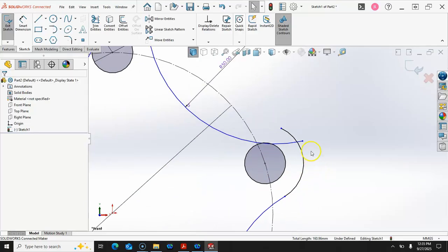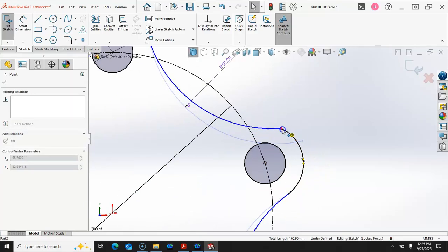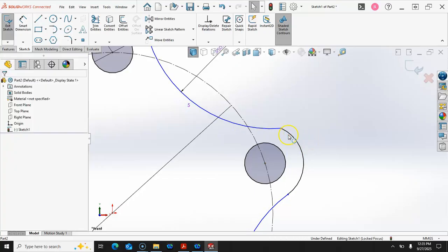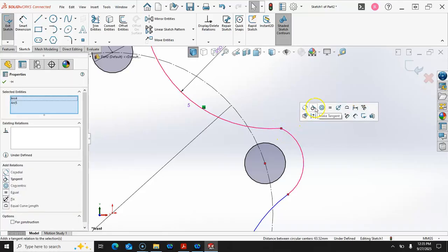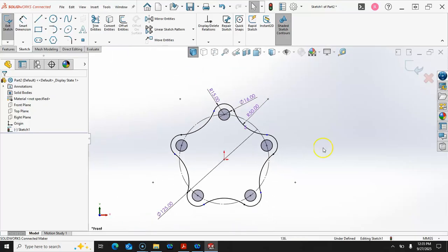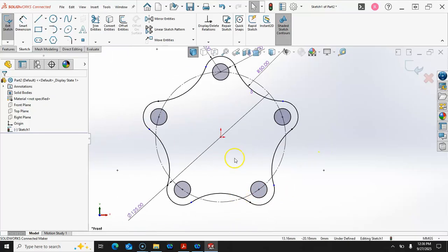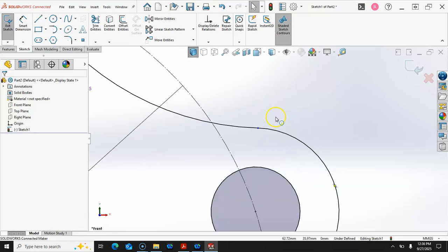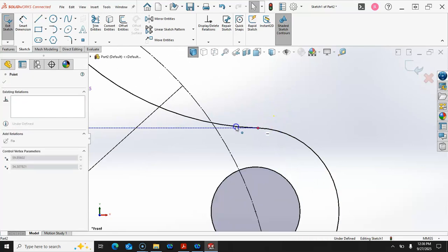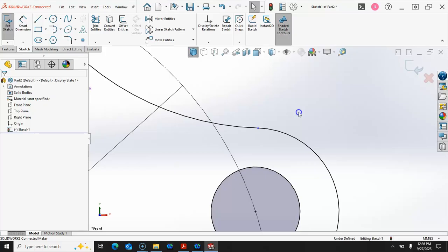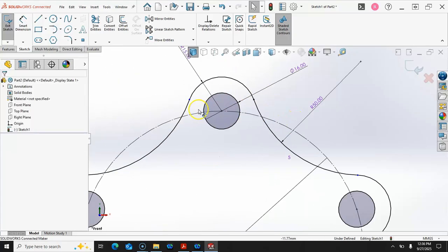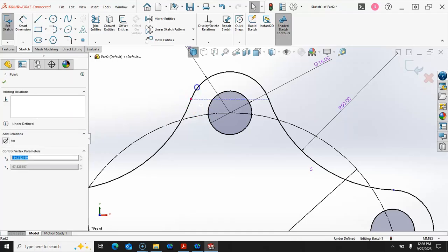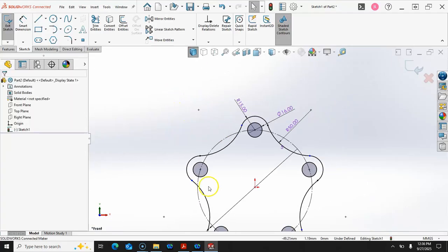All right, so not great, not terrible. First, let's connect the endpoints. Dragging to where I see that concentric, and then select, Control Select, go into tangent. That wasn't too crazy, but I do have some blue endpoints that makes me wonder what's going on there. It may have just not solved, and there are times where the geometry, based on what I told it to do, I may not get those blue endpoints.